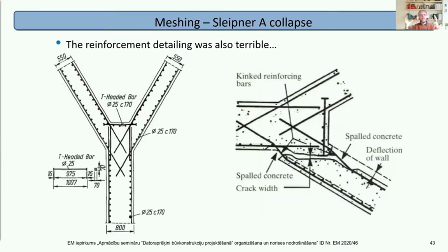So the overall behavior will be the same, localized behavior will be quite different, and there comes a point when you don't apply loads by a knife, hopefully, on your structure, but the beam connection does become effectively an area, or the bolt becomes an area, and so on. Yeah, there comes a point when you have to remember that a point load application is not a mathematical point.